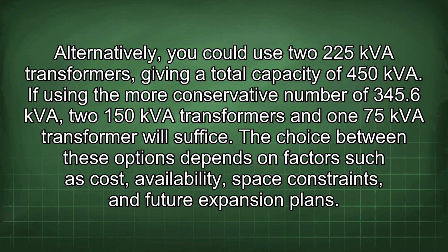Alternatively, you could use two 225 kVA transformers, giving a total capacity of 450 kVA. If using the more conservative number of 345.6 kVA, two 150 kVA transformers and one 75 kVA transformer will suffice.